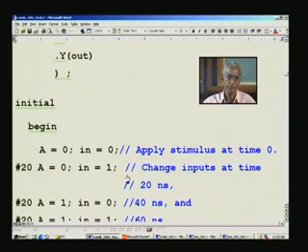After 20 nanoseconds. So, you mention this special marking for indicating that it is time, right. This is how Verilog recognizes that you are mentioning a delay of 20 nanoseconds, and only then do I need to apply this. Are you clear? So, after 0 nanosecond you apply this, it interprets like that. Then when it comes to this statement, it says wait for 20 nanoseconds.